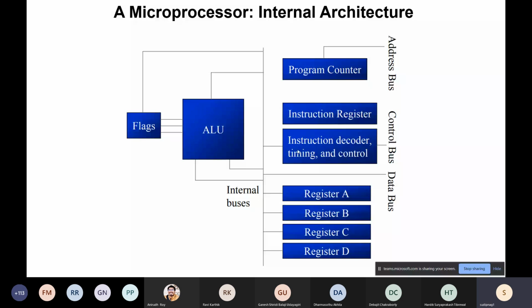There is another concept of pipelining. Pipelining means once the first instruction is getting decoded, the second instruction is fetched and kept in another instruction register or another register in between. So that is pipelining. In certain advanced microcontrollers only, you keep a queue of instructions.